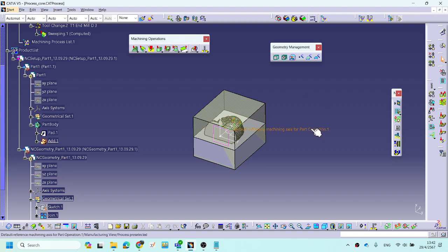Okay, in this video I think that's enough detail, right? I taught you how to create the surface from the point cloud, and after you got the surface and solid, how to use the close surface command in the part design to make the closed surface into one solid model, and use that part for making a mold, a cavity mold and core mold.